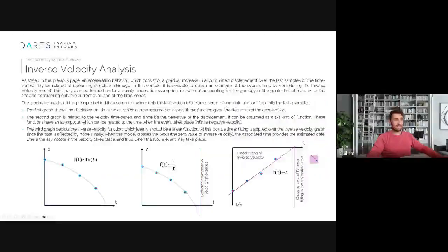What's going to happen? You can easily perform an InSAR velocity analysis, which is a very first approach. Of course, here we are not considering geotechnical parameters, like if you were in peak conditions regarding the friction angle and now you are in residual conditions, residual friction angle, you had cohesion, now you don't. We don't take into account thermal effects, which could even accelerate the displacement you are observing.